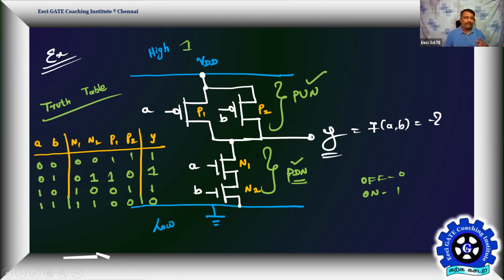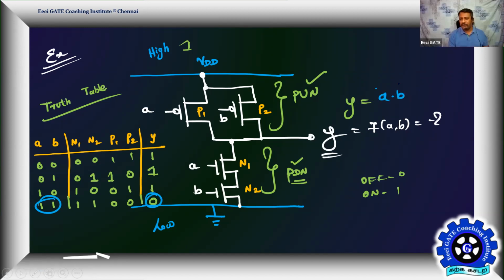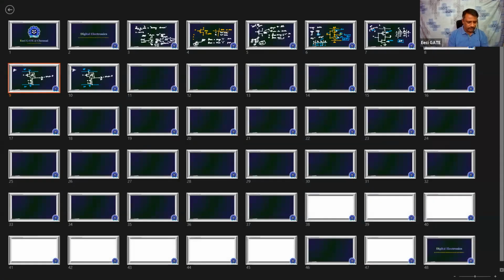First, let us conclude. So now we have a CMOS digital logic circuit. Tell me what is the connection between the output Y and the inputs A and B. What digital logic function is this implementing? NAND, sir. Y goes to 0 only when both A and B are equal to 1. Therefore, Y is equal to (A and B) whole bar. This is CMOS NAND logic, the CMOS implementation of a NAND gate. Instead of logic, you can call it a CMOS NAND gate.